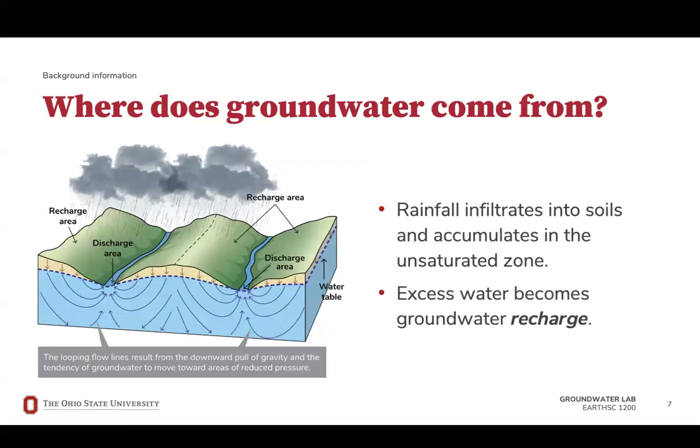Infiltration occurs when surface water, such as rainfall or snowmelt, seeps into the soil and moves into the pores and cracks of rocks. Water is pulled down into the soil by gravity and capillary action, filling up the air spaces between rock and soil particles. Infiltration is influenced by factors such as porosity, how much water the soil can hold, and permeability, how fast water can flow into the ground. Areas with vegetation, low slopes, and warmer soil temperatures tend to have higher infiltration rates.